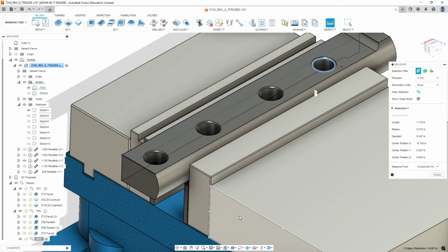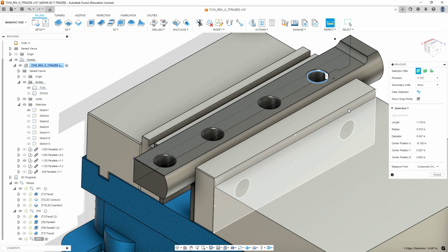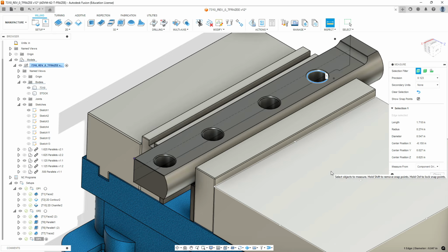Drill bits are the most efficient way to remove material for this type of operation. So we're going to go ahead and drill it first, and then we're going to come back and open the holes up. We're going to drill each one. We're going to spot drill each of these locations. We're going to drill each one of these locations. We're going to profile the inside of the hole, and then we're going to use a chamfer mill to do the chamfer on the edges.